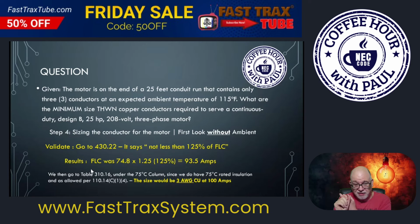All right, so that means that if we were to take that 100 amp conductor, which a 3 is good for, and now we use the multiplier for the ambient correction against that, what would that give us as an ampacity? Well, 100 multiplied by 0.75 will give me a conductor that's only good for 75 amps. Well, that's less than the required 125% conductor sizing based on 430.22. So we already know that's not going to work for us because of our condition of use, okay? So just remember the two. On an exam, if they don't ask you for the ambient and they don't say anything about more than 3 current carrying conductors, this is it right here, straightforward.